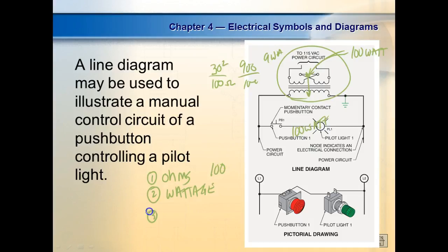What's the third thing it's rated in? It's not rated in a voltage. So over in our solid state class, we're learning how to do basic design of regulated power supplies. And that's what you got to understand. You calculate the size of a resistor. You can't just say I'm going to round up or round down. It depends on which way the tolerance is going to go, right?